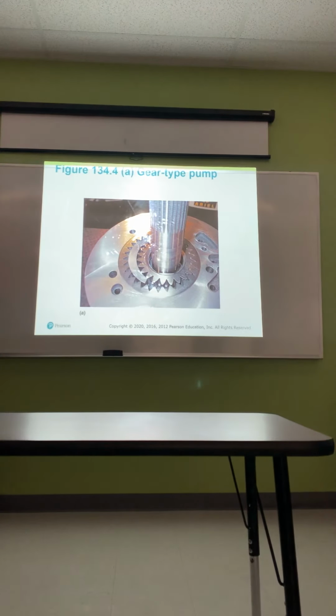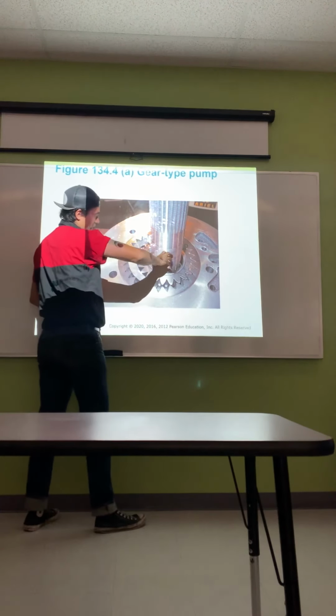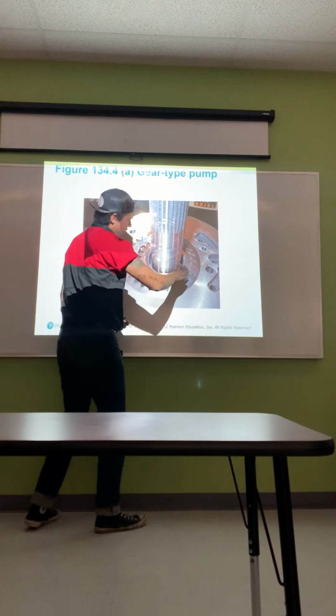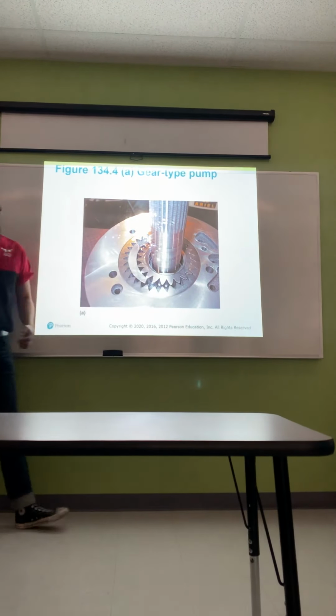So this is a gear type pump. It actually uses gears. When it rotates, it's meshing together with the outer ring and the sun gear in the center, pressurizes the fluid, and then pushes it out.